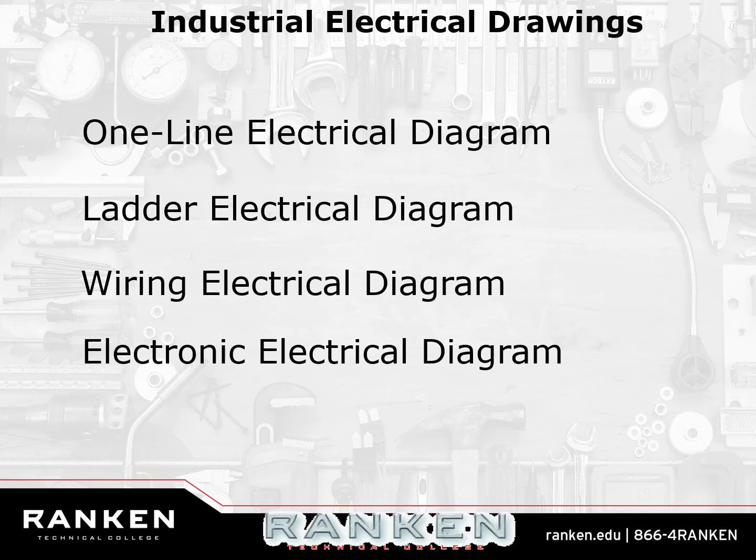That shows me physical locations, the actual terminals. Most times it'll tell me the wire number, and most of the time it'll tell me the wire color, the gauge of the wire, and all the information that I need to know in order to physically wire it up. That's what a wiring diagram does for me. And then a schematic usually shows component level material, right?